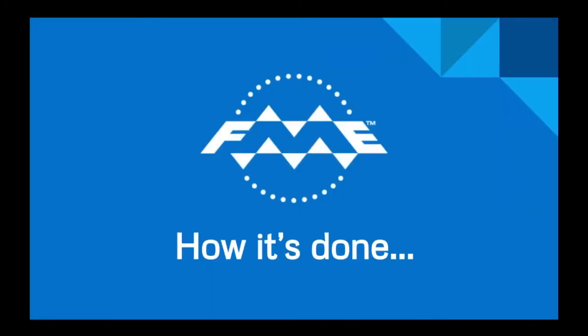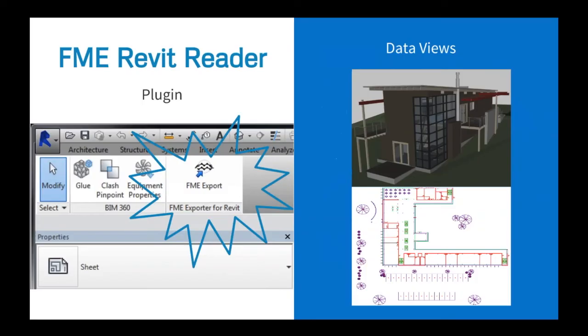And it turns out it's not that hard to do. But what we have to do first is inside Revit, we use this FME Exporter that is now there. You can install that. It's downloadable from our site. You bring up your model, you click that, and then you can get your extract out so that FME can then read it and work with it afterwards.